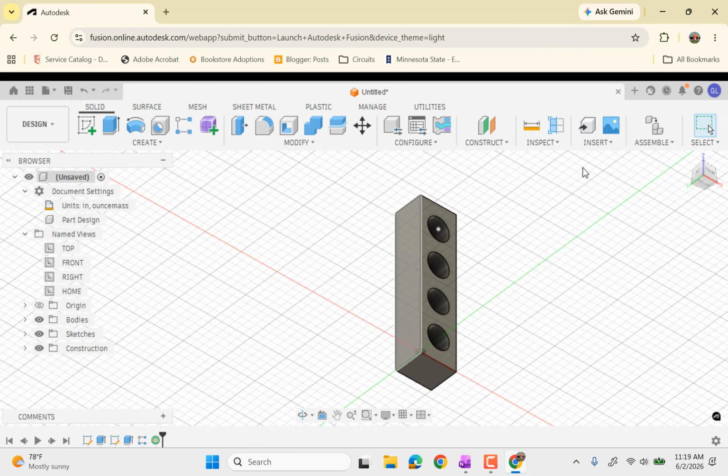But it's not a pattern that we can use here. You could think like, oh, well, it's a pattern. We want to flip it over here. But none of the pattern tools that are given are going to let us do that. What we're going to do instead is make the cutout on one side. Then we're going to make a plane down the middle. And then we're going to use the mirror command to make something that's symmetric about that plane we just made. And that'll cut it out at the other side. Can you sort of physically visualize the way that works?